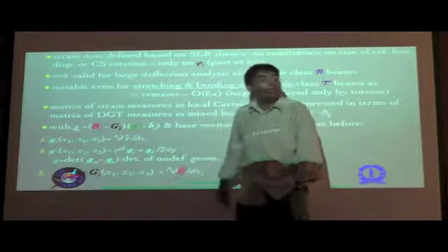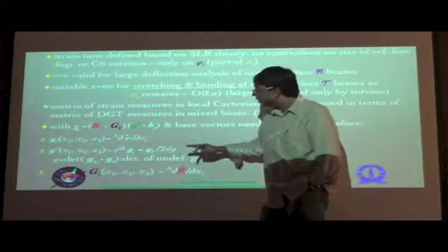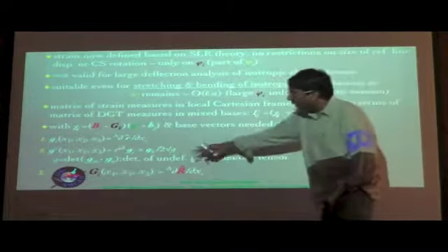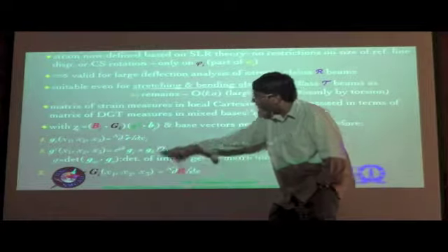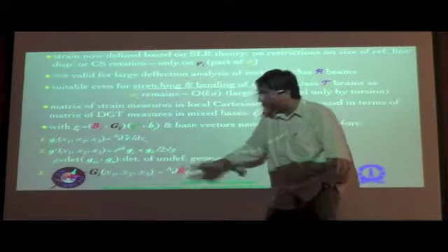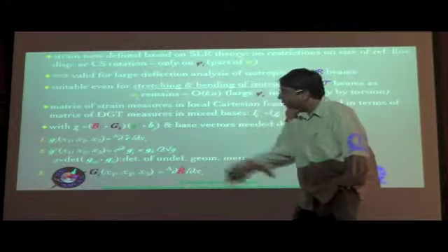You need the contravariant base vectors, but in the deformed configuration you need only the covariant base vectors, which is basically this, and that again is formed very similar to in the undeformed configuration. Instead of taking the derivative of small r hat, we have to take the derivative of big R hat with respect to the xi's to get all three of the covariant base vectors there. So this is the general expression that we have there, and so let's recollect.